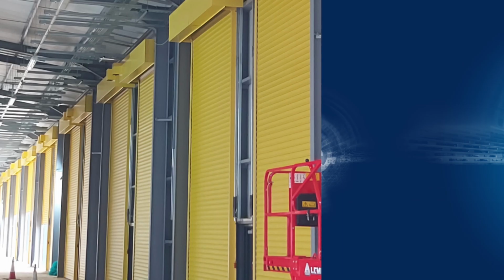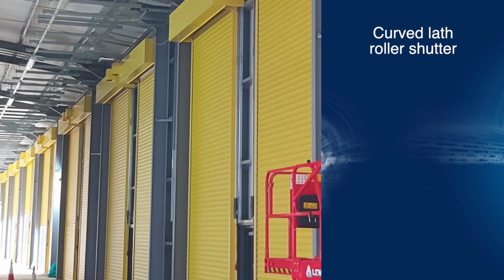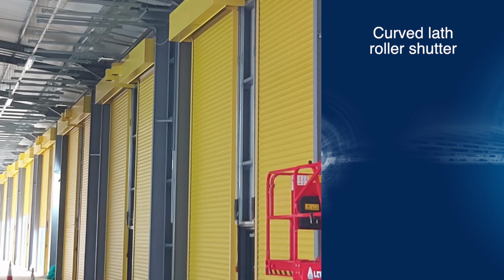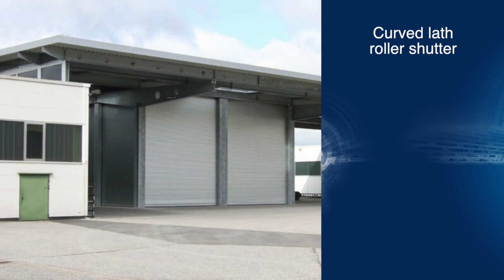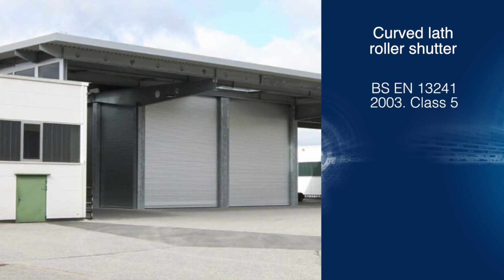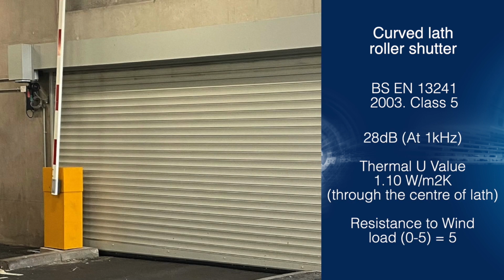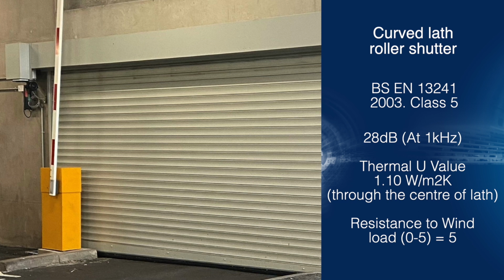For enhanced thermal insulation, consider the curved lath roller shutter, typically crafted from 2 layers of robust 95mm curved galvanized steel, filled with a CFC-free foam insulation. This shutter is compact and a much lighter weight option. It undergoes wind load testing as per BSEN 13241, providing an acoustic reduction of 28 decibels at 1 kHz. This product is ideal for settings prioritising soundproofing and security, whilst offering an exceptionally high level of insulation.